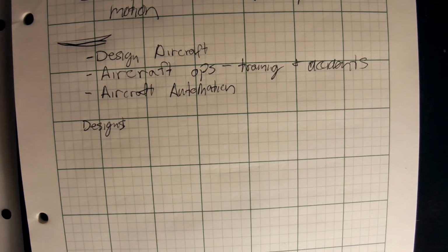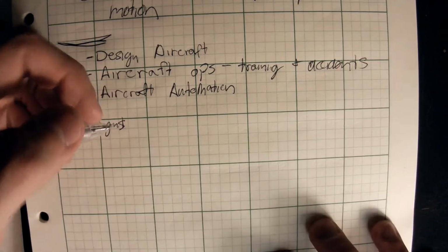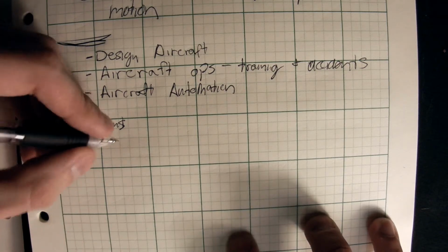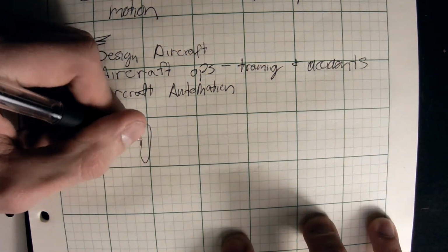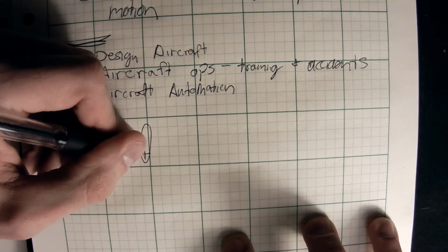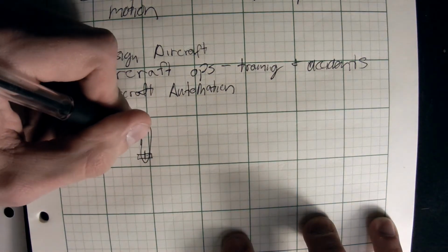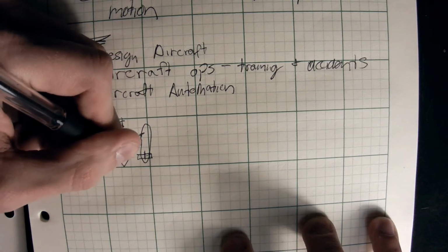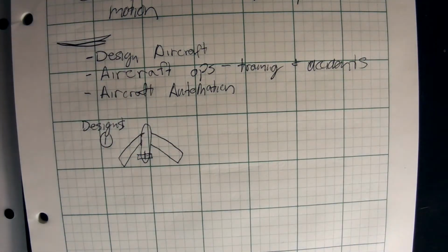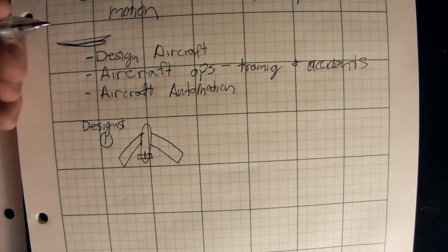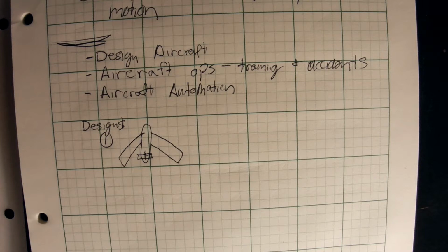For roll stability, there are a couple of things that affect it. One is swept wings. I'll just draw a quick example of what that looks like. So we have these swept wings back here. We'll go over it in more detail later on, but just trust me for now, that increases the roll stability, as in how likely it is to bank left or right.